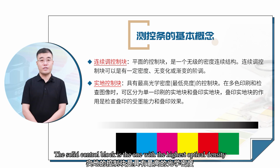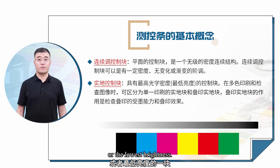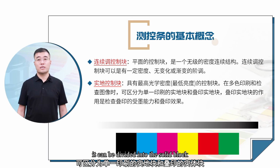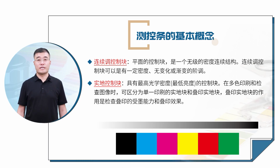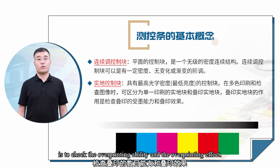The solid control block is the one with the highest optical density, or the lowest brightness. When it comes to multicolor printing and image inspection, it can be divided into the solid block for single printing and the overprint solid block. The function of the overprint solid block is to check the overprinting ability and the overprinting effect.